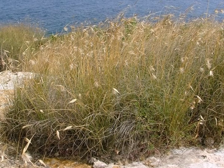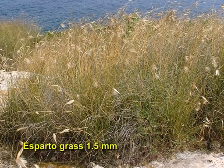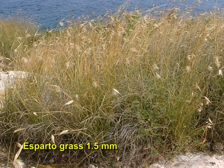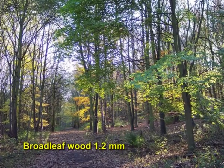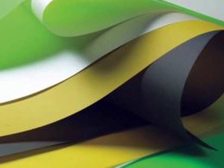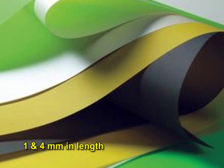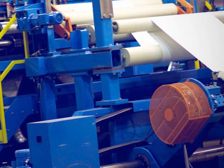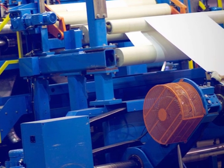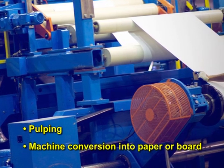The individual fibers of cellulose are very strong and of varying length, that is esparto grass 1.5 mm, coniferous wood 3.5 mm and broadleaf wood 1.2 mm. And those that are preferentially used for paper and boards are between about 1 and 4 mm in length. Then the manufacturing process. To manufacture paper or board, there are two basic processes. A. Pulping, then B. Machine conversion into paper or board. Let us discuss the pulping first.